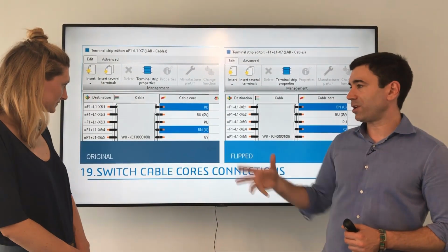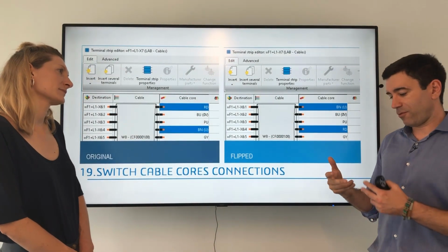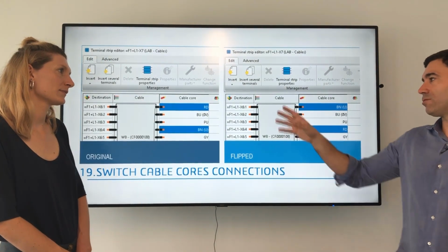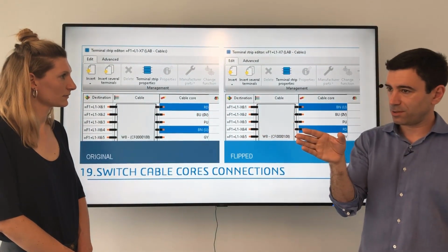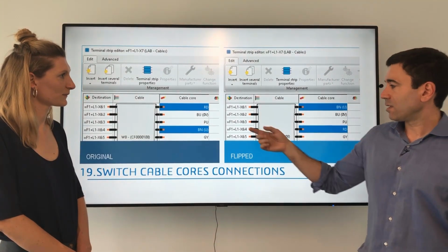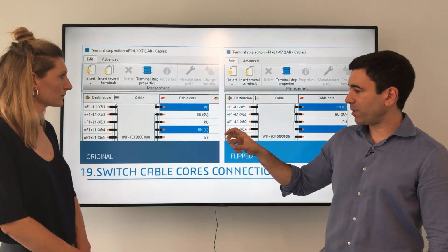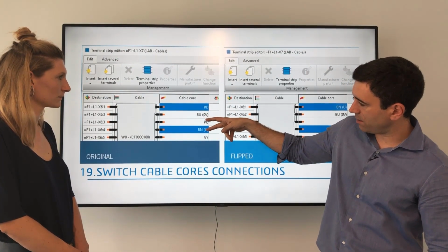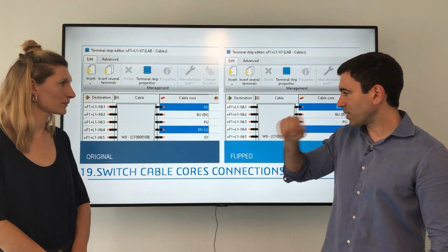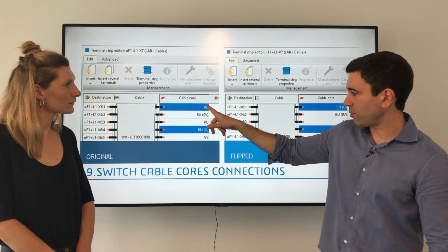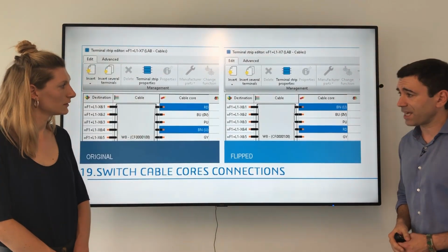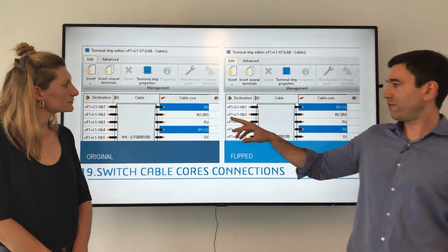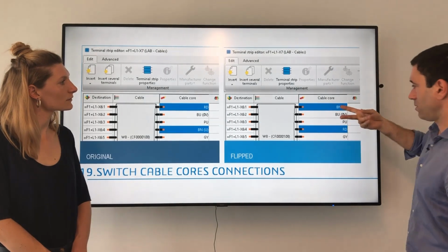So for circuit design, when you create connections and for some reason you need to change a connection because it's wrong, you had to go to that particular connection, delete the connection, and create a new connection. This is an example from a cable, and if you want to change the connection, because actually the first goes here and the fourth goes on top, you had to delete this one, delete the other, connect this one, connect the other. Now, you just need to select both and select the option flip the connections, and they will just flip like this.